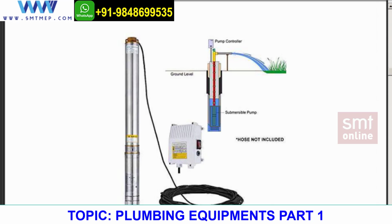If we open this completely, we do have a kind of mesh or a strainer over there. Behind that we do have a motor which rotates, and this wire will also be completely submerged. For example, if it's 100 feet, 100 feet of wire will be there, and connections. The moment we open this, there will be rotating energy because it's a centrifugal pump again. So rotating energy will be converted to potential, then potential will be converted to pressure energy. Why? Because of this pressure, the water will be coming over here. We do have this generally in our homes in India especially.